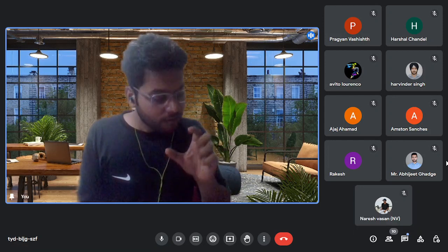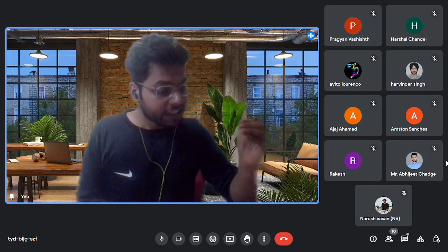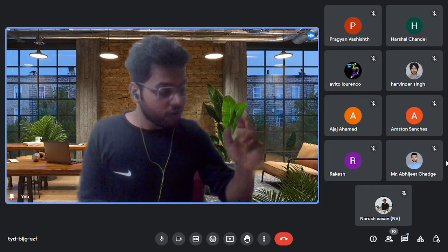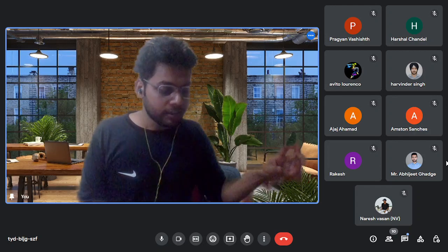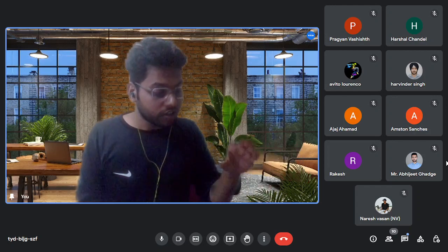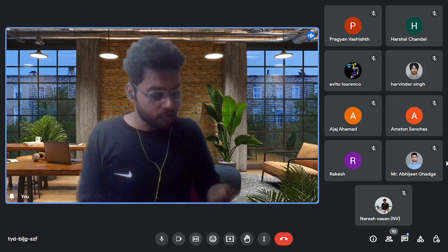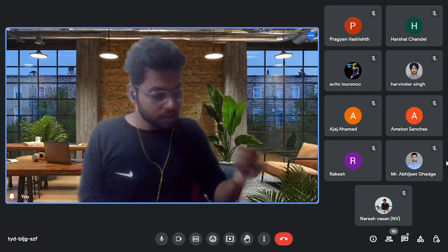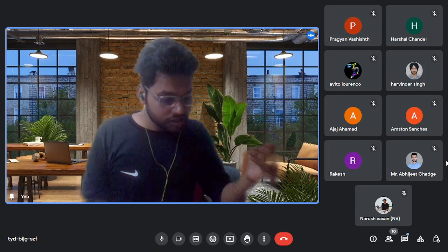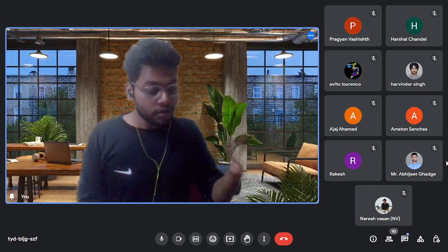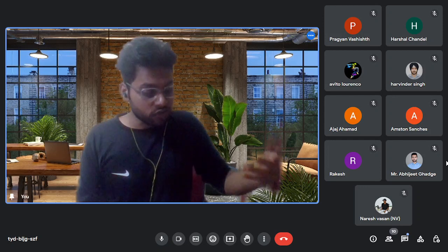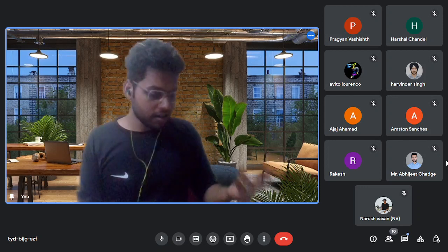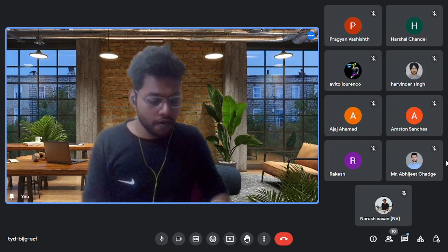Because of the high temperature, lubricating oil will form vapor and then condense, then oil mist will be created, and the oil mist detector will detect the formation of oil mist. If there is more oil mist, there will be a chance of crankcase explosion, and the lube oil can catch fire. Yeah, I was right, guys.